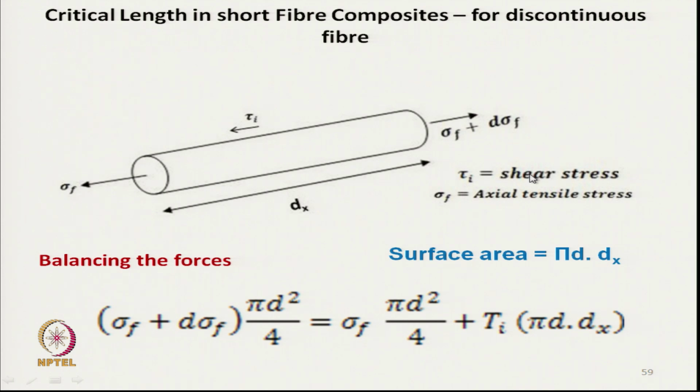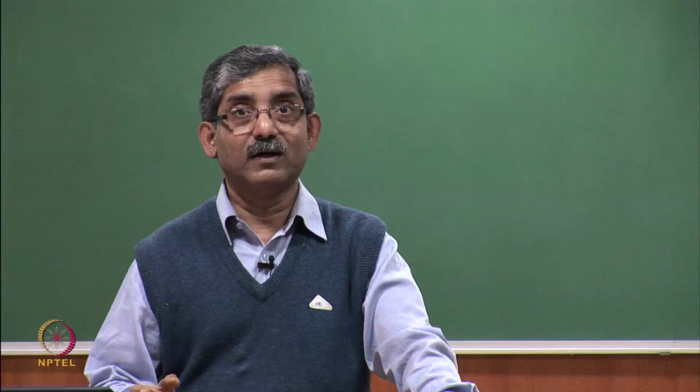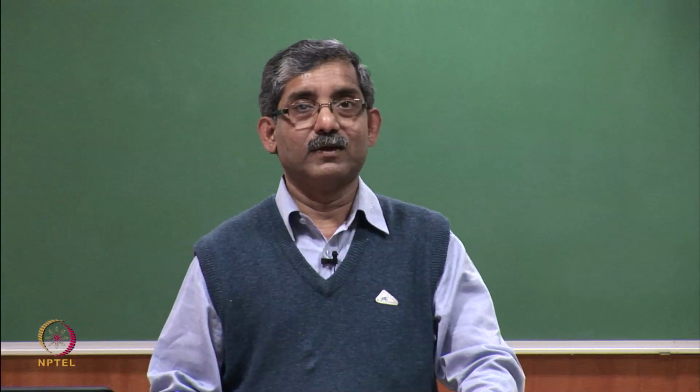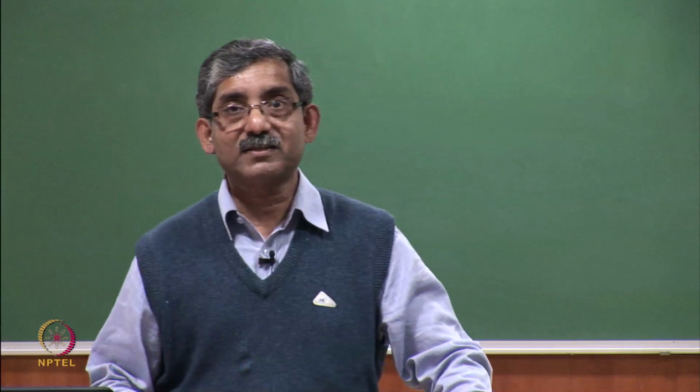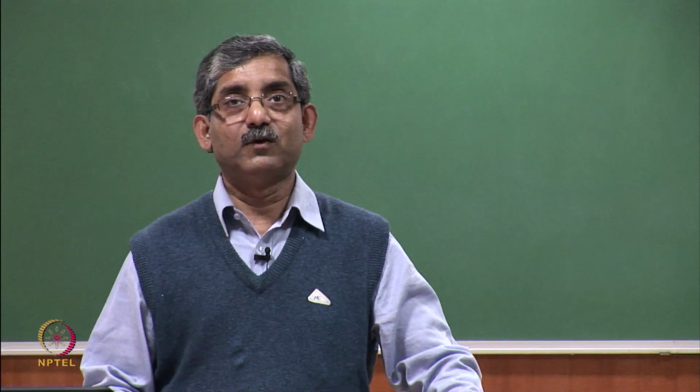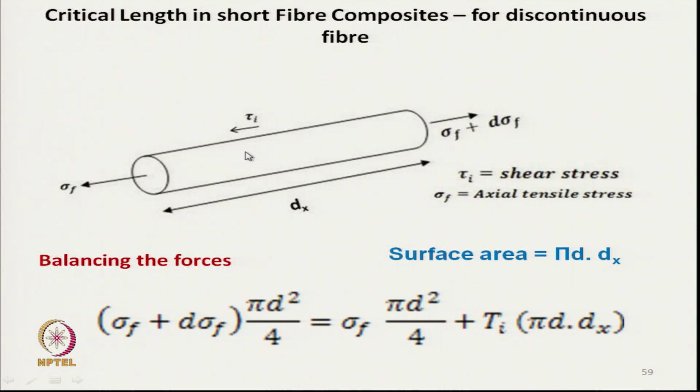So, critical length is very much important for short fiber composite, and it depends on the shear stress between the fibers and matrices.